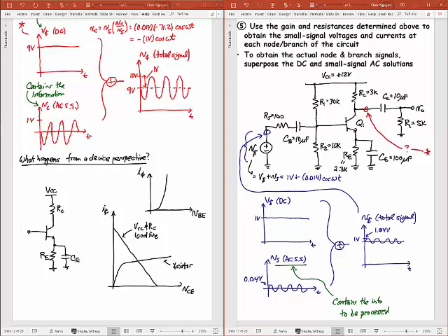I put that load line right there, and then this is a plot of IC versus VBE. This is sort of like a diode plot, because the input to a bipolar transistor looks like a diode. You're going from the base to the emitter, and that looks like a diode that you're turning on. So that's why that looks like a diode turning on. But what did we really do to this? What we did was we biased this device.